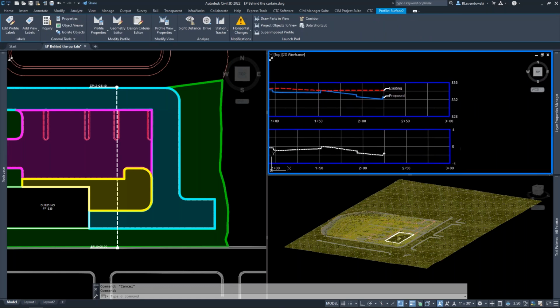These are two separate profile views. This is down at elevation 0, near elevation 0, whereas my site is up around 800. So specifically, what is a volume surface? It's not a volume. In fact, it's a tin surface whose elevations are the delta between the two comparison surfaces.